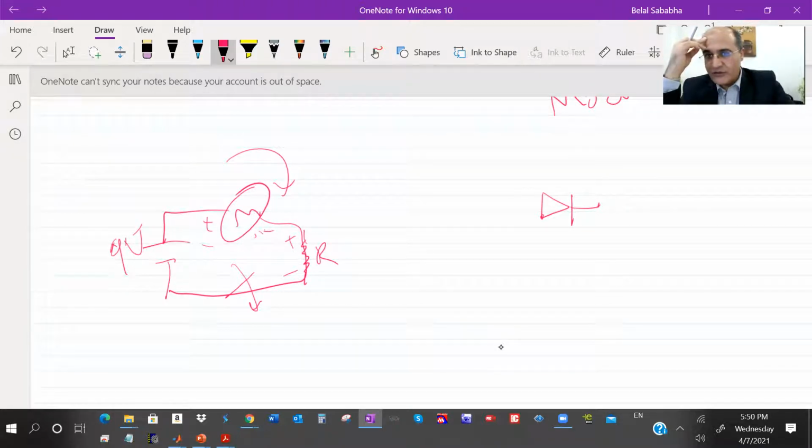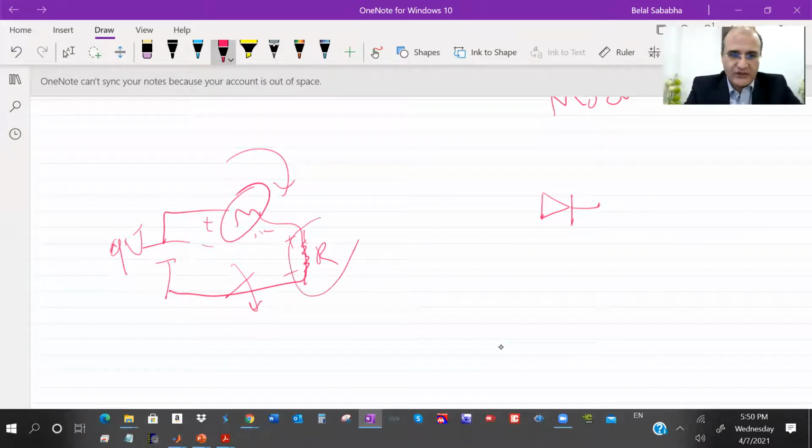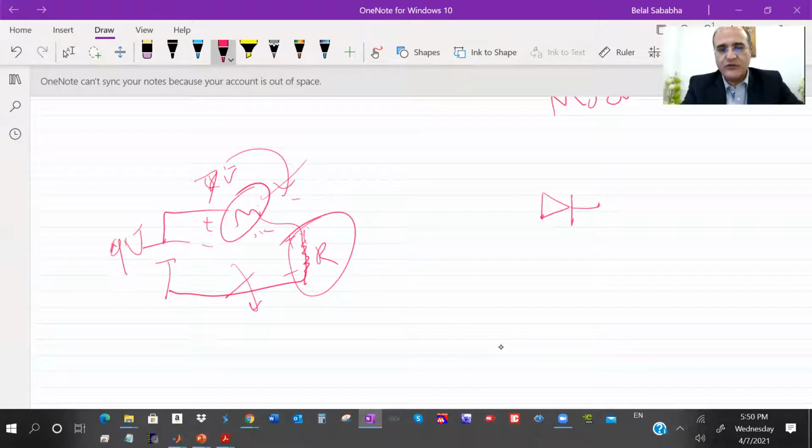That is completely true. However, there are some drawbacks here. First, you're wasting energy, wasting power in the resistor. Second, the motor, for example, has to have at least 8 volts or 7 volts across it to work, depending on its system. So after a certain point, you're going to go below 7 volts and the motor will stop, right?